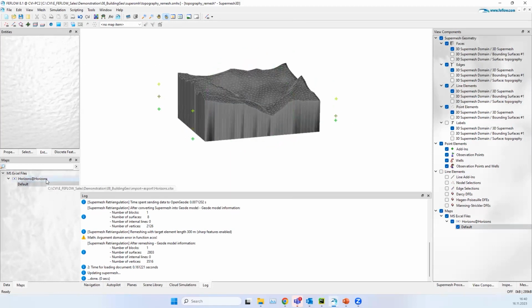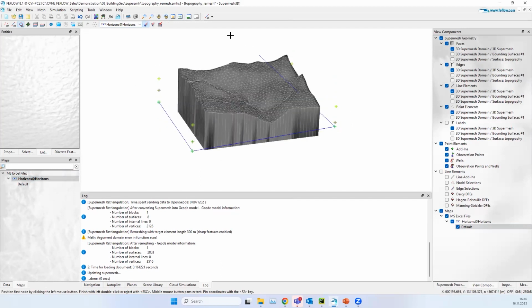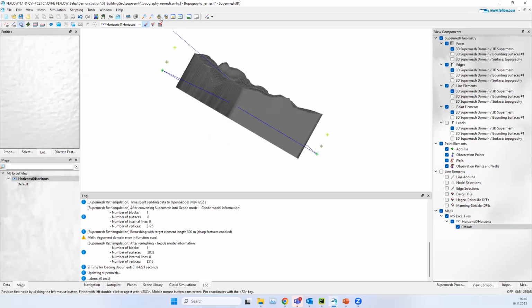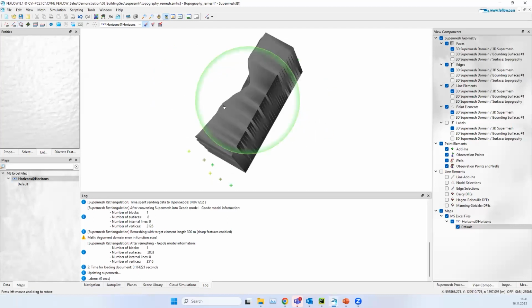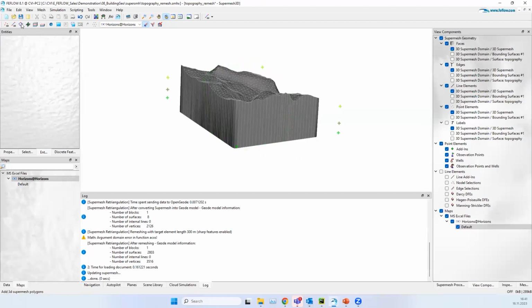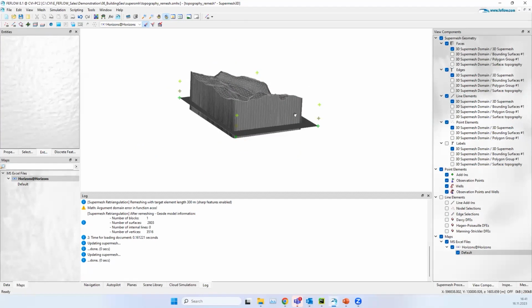And then we can use the tool to snap, and then we can start digitizing our geological model. So we can snap to any external data or part of the domain. I just make the surface a bit bigger so that it's visible for you. And then we can keep rotating the model. And then with enter, we can close, and then we have a new surface.